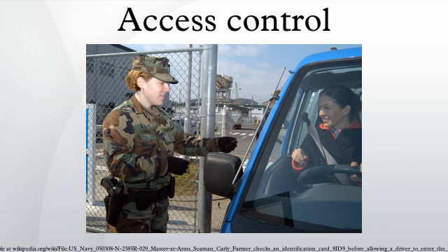Types of readers. Access control readers may be classified by the functions they are able to perform. Basic readers simply read card number or PIN, and forward it to a control panel. In case of biometric identification, such readers output the ID number of a user. Typically, Wiegand protocol is used for transmitting data to the control panel, but other options such as RS-232, RS-485 and clock and data are not uncommon. This is the most popular type of access control readers.